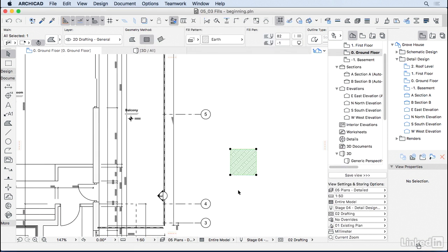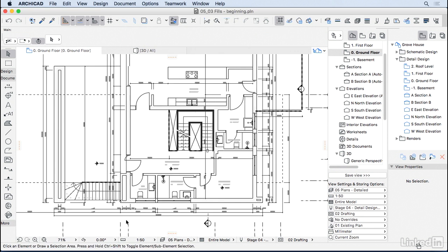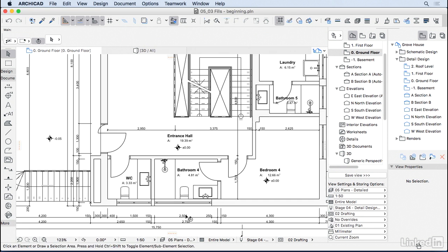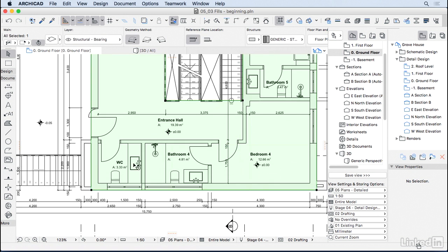When we created those slabs here, if we wanted to, we could have chosen a cover fill for the bathroom, for instance, to have tiles. You don't really need to create the 2Ds. It's best if you actually do it in the slab. So I'm going to take a piece of this slab out. I'm going to just add a new node here, offset this edge. And that's actually the way you do it. You need to have two different slabs to have two different properties. And that's okay because later on we're going to have those slabs in different composites.